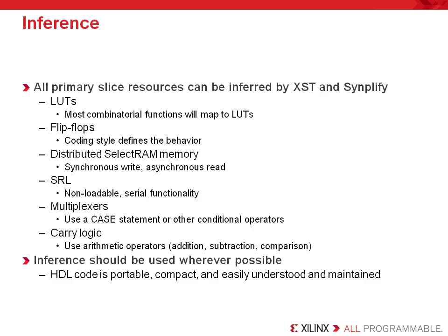This slide is intended to guide you to the proper HDL coding style so that you get what you want out of the FPGA. One of the biggest challenges for new users is to make certain that they are inferring the appropriate resources. First of all, one of the best ways to check that you're getting the resources inferred is to check with your tool's schematic viewer. That's your synthesis tool schematic viewer. You should use the technology viewer to understand what Xilinx primitives are inferred by your synthesis tool.